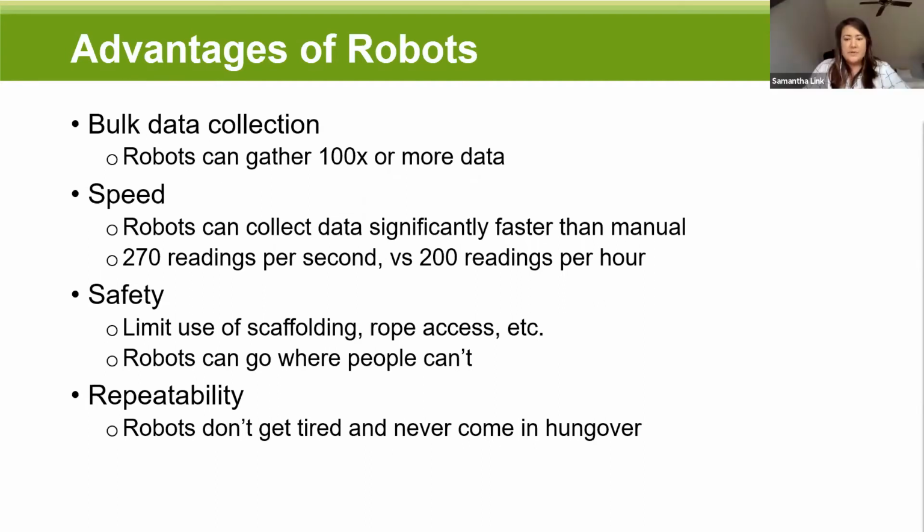Gotcha. So what's the minimum clearance for the crawler to travel up a shell? For example, to scan a digester shell that has a liner of plates covering access to the outer shell. Just as a note, the scan is from the inside while a maintenance outage is also in progress. Yeah, so our crawler needs about 6 inches of clearance, or at least the robot itself is 6 inches.